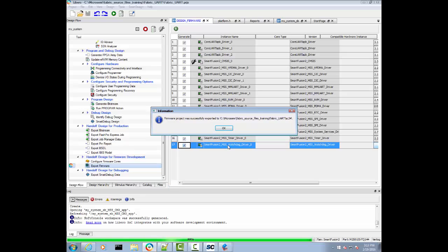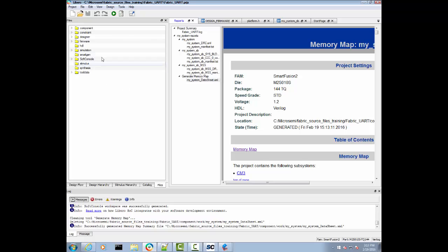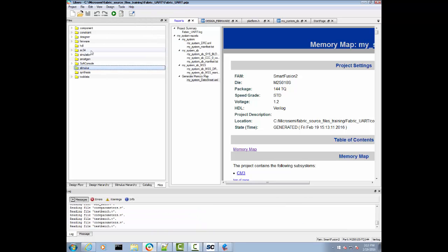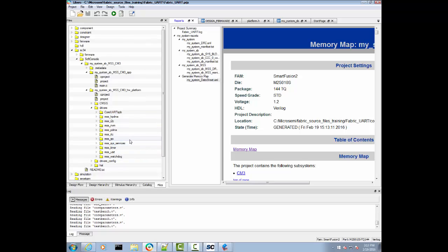The drivers are toolchain independent. So you could still do that. So you see what you would get in that case. There's my SE34, and we made a project and then a reference project here, but there's all your drivers right there. You can just bring all those in. So that's another way you could do it. You just have to make sure you don't try to open this project in SoftConsole 4.0 because it won't work. But the drivers would be okay. You could just bring all those in. Perfect. So that's another way you could do it.